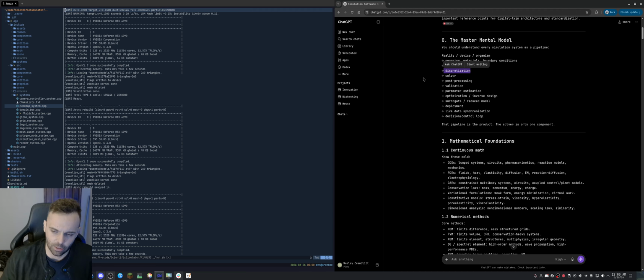Discretization, this is how you represent these equations and geometry, all of it, in a finite space. So lots of ways to do this, lots of methods like finite difference, finite volume, finite element, spectral. There's a bunch of them. It's kind of how you integrate those equations, create a fixed finite domain, and solve the equations. It's always an approximation, and there's a way to calculate the error of the approximation to know how accurately you're following the physics.